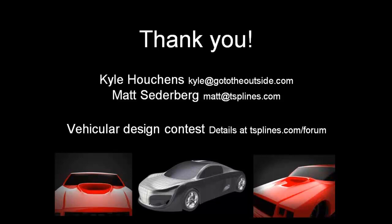Okay, so there's a question, how about the end gun at the bottom of the hood? Why doesn't that cause a problem? So that's going back to Kyle's part of the demo. With T-splines, it is possible to have n-gons in the surface. They are not as smooth as the rest of the surface. They'll be G1 smooth, so tangent continuous. So the surface just behaves as though there's a star point in the middle of the n-gon. So avoid them if you can, but if you can't, then it will be fine, and that's kind of the surface quality that you will have.